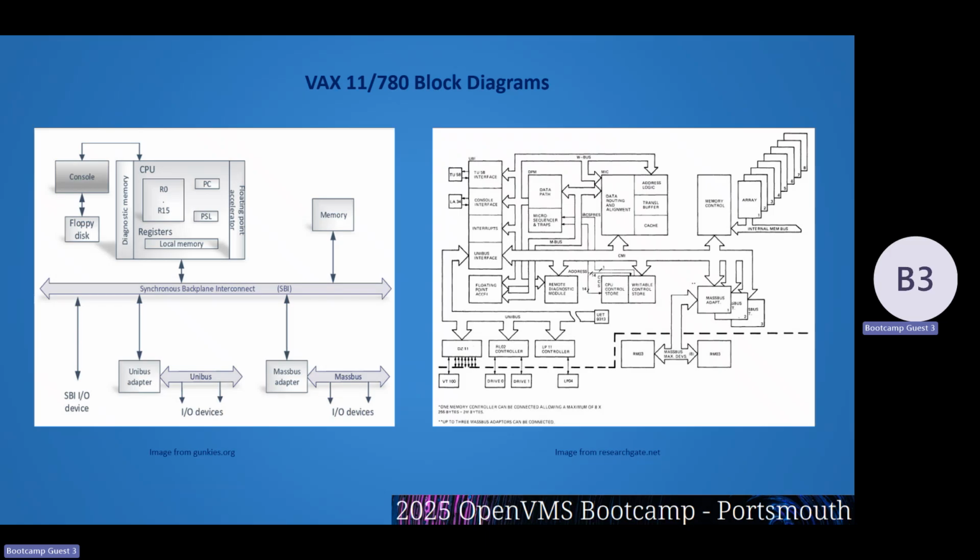On the right is a more detailed block diagram. The data paths to make the CPU work. You had some remote diagnostics in here, writable control store. You went from the Unibus interface out to the Unibus. You went out to Unibus controllers, where you could connect things like this guy, which is an RL11, 2-disk, 2 megabyte disk controller.